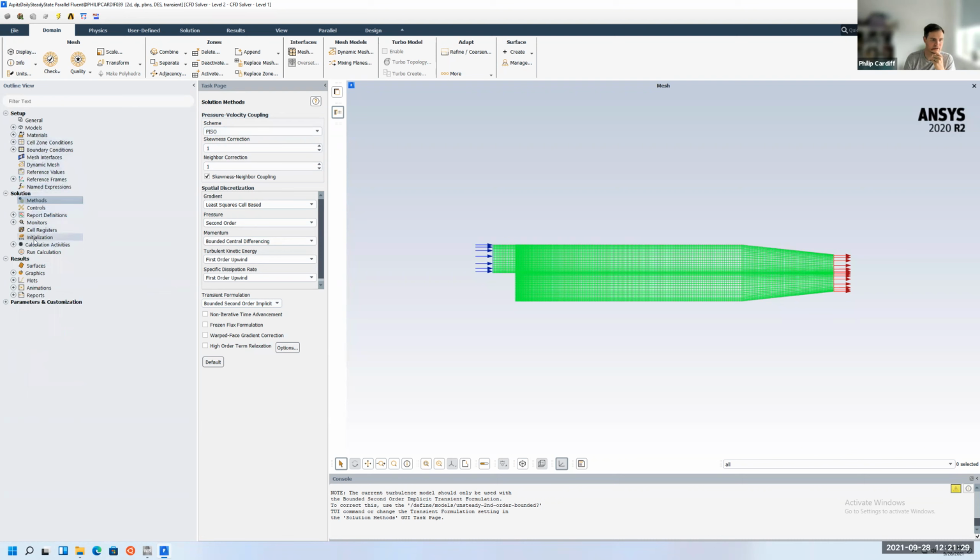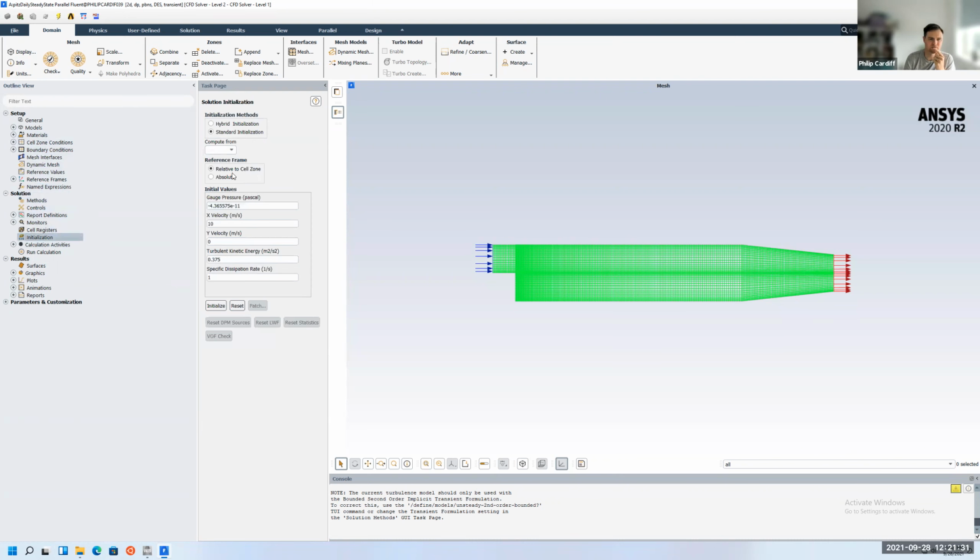We're going to initialize the flow. Rather than giving it a good guess everywhere, we're actually just going to set it to be 0 everywhere. If you imagine, it's like we're just turning on the experiment, the flow is not moving, it's all just settled laminar flow, and then suddenly we just turn on a big fan that starts blasting in high velocity air. So we're going to initialize that to be 0.